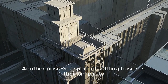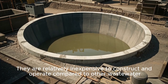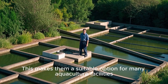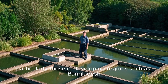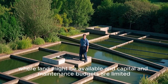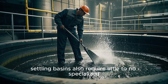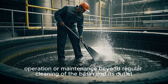Another positive aspect of settling basins is their simplicity. They are relatively inexpensive to construct and operate compared to other wastewater treatment methods such as filtration or aeration systems. This makes them a suitable option for many aquaculture facilities, particularly those in developing regions such as Bangladesh, where land might be available and capital and maintenance budgets are limited. In addition to the low cost of construction, settling basins also require little to no specialized operation or maintenance beyond regular cleaning of the basin and its outlet.